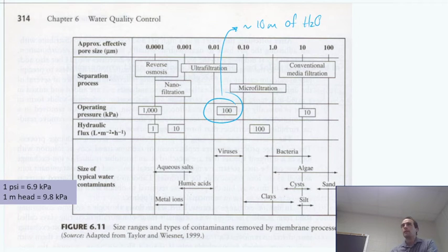So that would be hydraulic head, right? If you put a column containing water and you stack it up higher and higher, that water is exerting pressure. It's like when you go swimming in a swimming pool and you go to the bottom, you're feeling some pressure based on the 2 meters of water pushing down on you. So when you get up to 10 meters of water pushing down on you, that's enough pressure to supply an ultrafiltration membrane in this area that can potentially remove most, if not all, viruses. So you definitely get all bacteria. And so this is a neat technology.